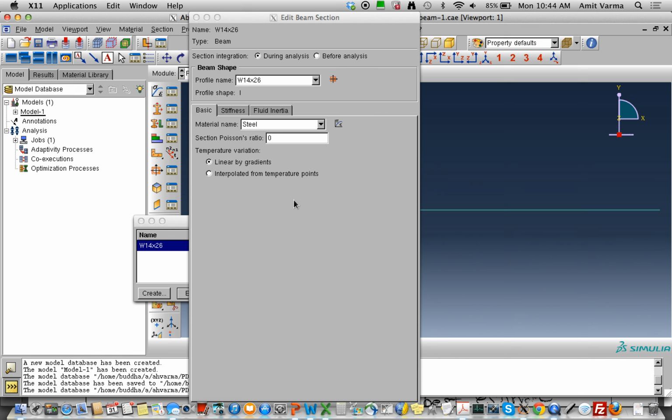It won't be a closed form solution by any means of the word. It will be an approximation, just like any finite element approaches, but it's going to account for the spread of plasticity along the length. Which means that when you're doing this analysis, you're using option number 1. Remember we had 3 options. This was 1, this was 2, and this was 3.